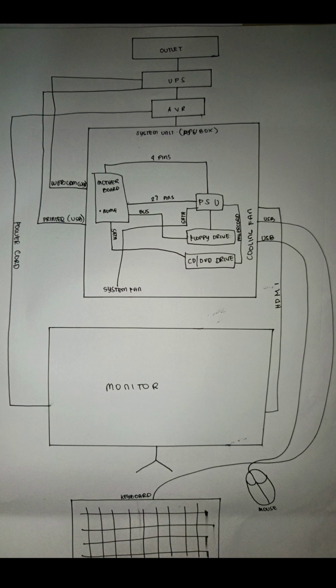First, Step 1. Power setup. Plug the UPS into the wall outlet and plug the AVR into the UPS. Plug the system unit and monitor into the AVR. This ensures both backup power and voltage protection.